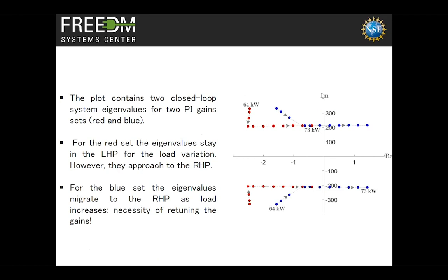So what happened is that if I use traditional PI controllers, which are common in the SST literature, if the load fluctuates too much, which is becoming more and more common in the distribution grid anyway because of high variability of loads. So for certain operating conditions, if you linearize all those nonlinear equations which I was mentioning in the last slide, you can show that the eigenvalues of the linearized system actually start migrating towards the right-hand side, which means I have Hopf bifurcation essentially.